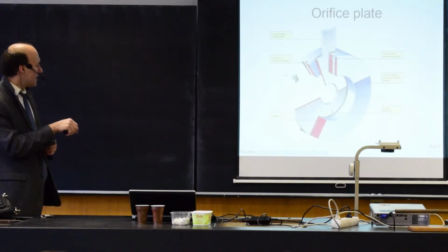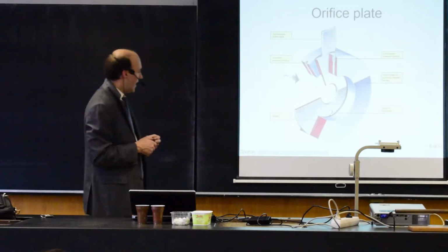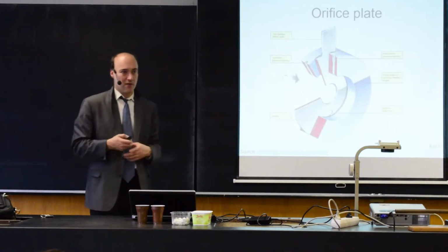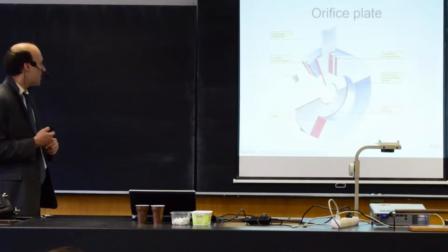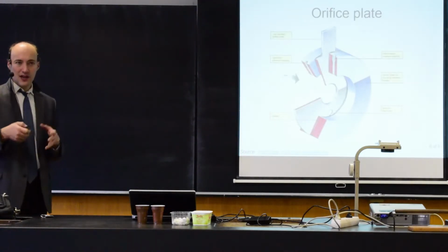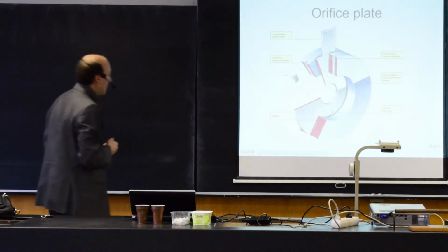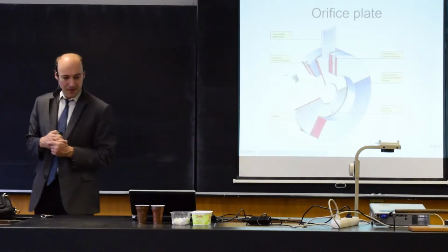You can see that here there typically is another small hole at the bottom to allow sediments, if they are present in the fluid, to escape. Here you can see that we have the two pressure taps, downstream and upstream. The distance from the orifice plate and also their diameter is also defined by a standard.